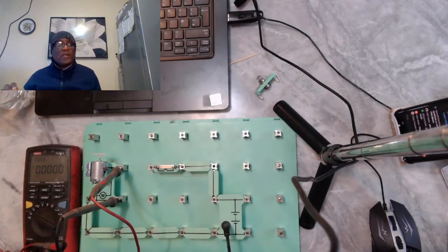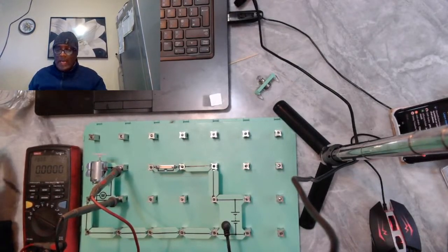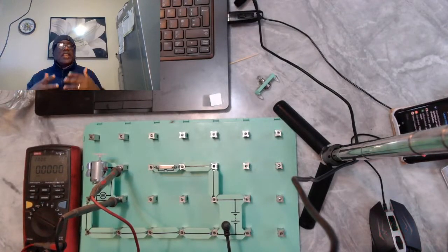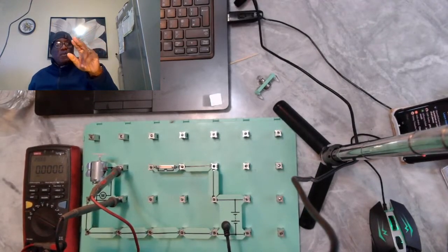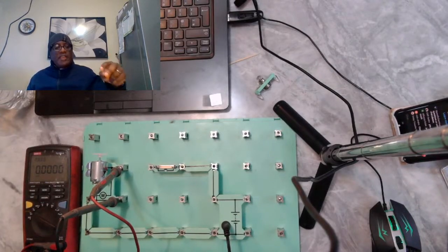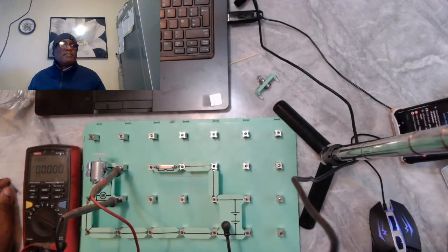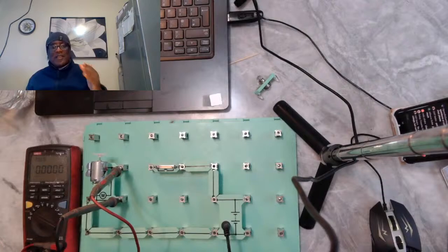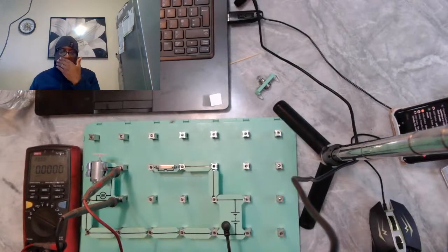What are you doing when you are looking for an open circuit as a technician? Let me say this to you. You check the two sides, your power and your ground side. The side that is going to have voltage is the side that has got an open. Get me right here? Let me repeat myself. I said, you check both sides one at a time. If we check the ground side, that's why I said it first.